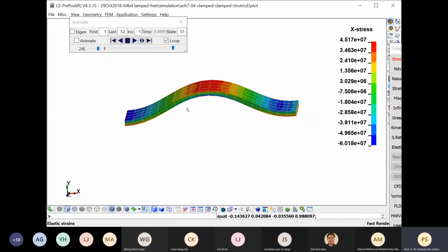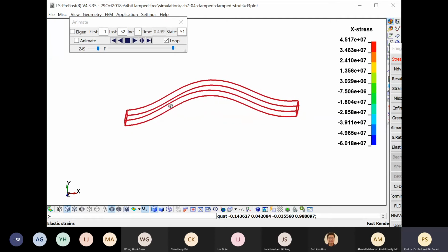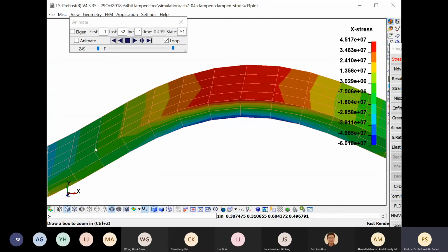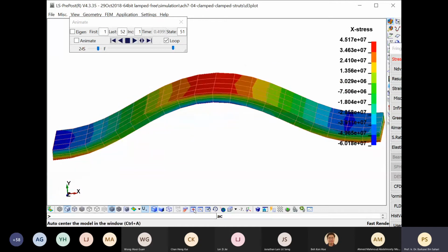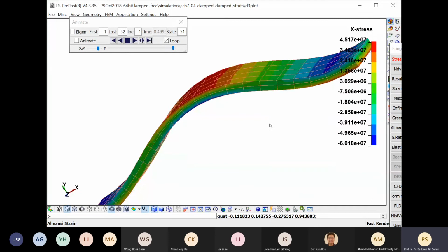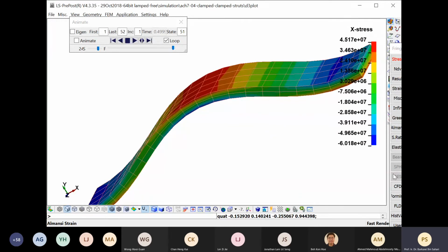So that means the distance between these 2 points, okay, can you see that? Between these 2 points, this point and that point, will be the effective length. So if I take 1/4 from there, 1/4 from there, that leaves me an effective length of half of the total length of the beam, of the column. So that's the meaning of distance between 0 bending moment according to the definition.